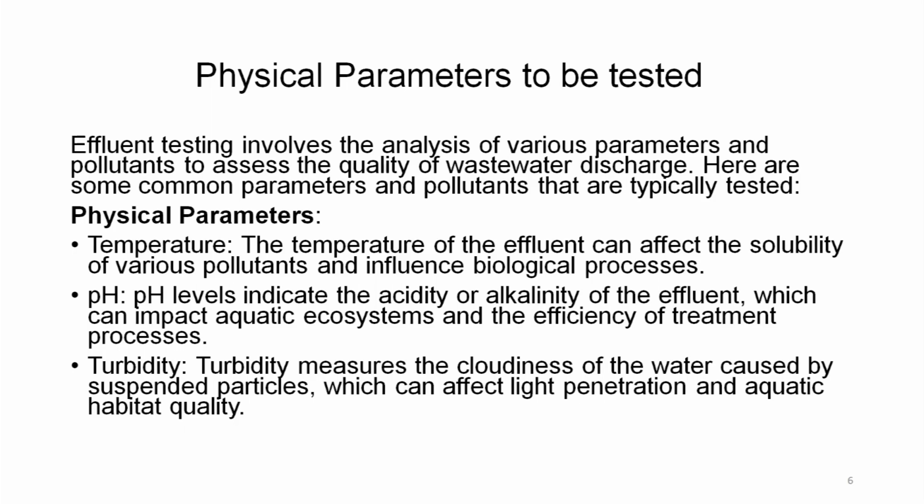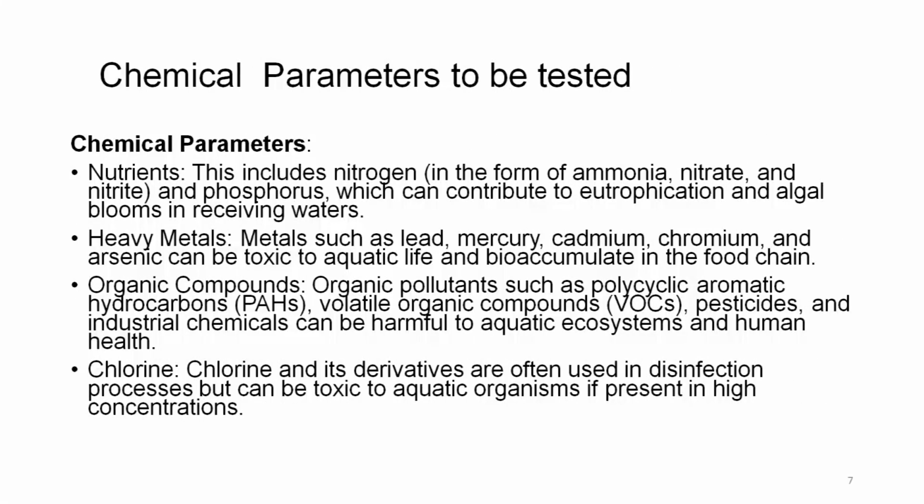I had mentioned earlier in one of the previous lectures that turbidity is equally notorious, because all these suspended particles do not let sunlight penetrate into the water bodies, and all the aquatic plants which are dependent on the sunlight for photosynthesis do not get sufficient sunlight. As a result, they die out, and therefore, this turbidity can be quite notorious.